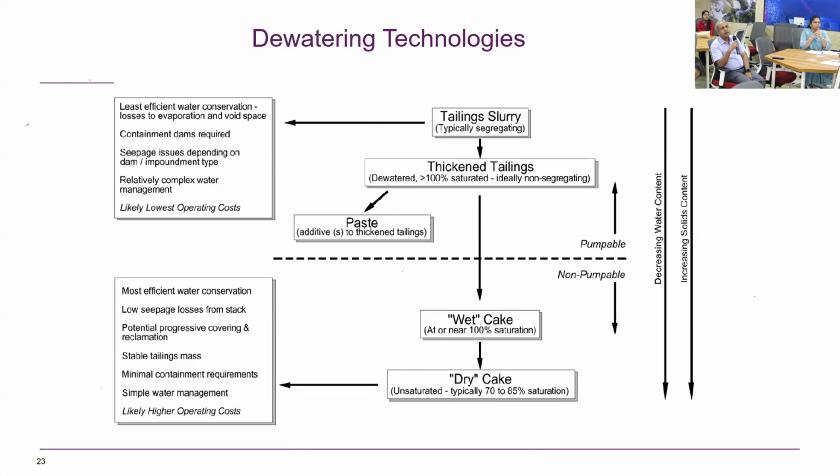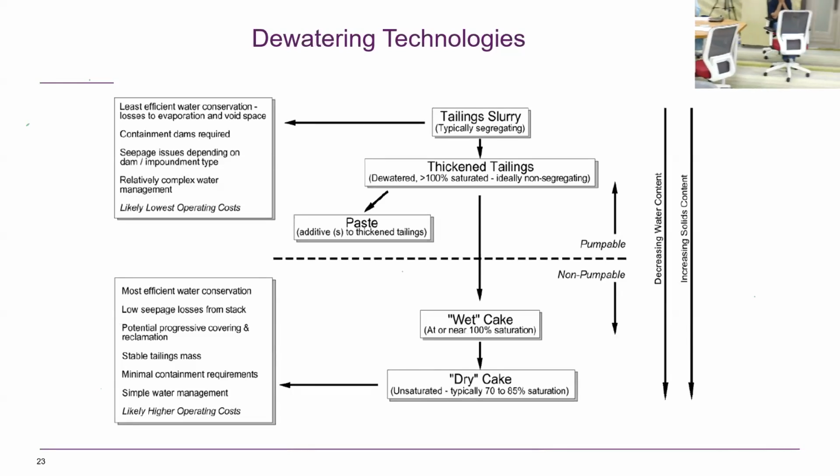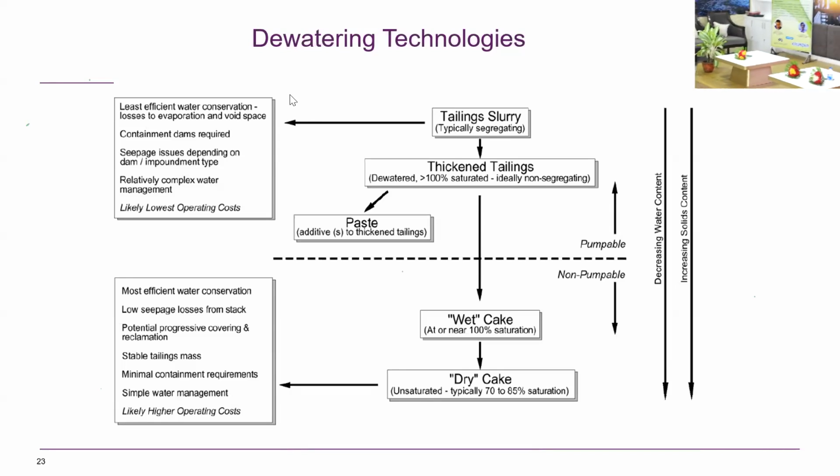The precautionary measure is, again, we monitor the pore pressure, because we know it is prone to static liquefaction. But in static liquefaction, there is a residual strength, so we have to make sure the material stays above the residual strength, because if it goes below, it will fail.